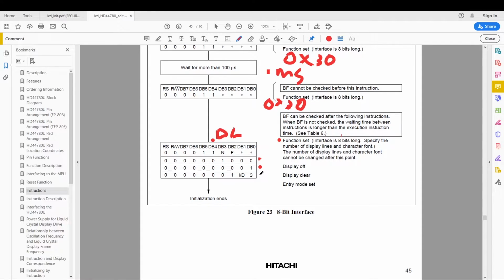And then you set the entry mode, where you set if you're incrementing or decrementing the register, and if you're shifting the display. Shifting the display will, in my case, be 0, because I'm not going to shift the display, and I'm going to increment.